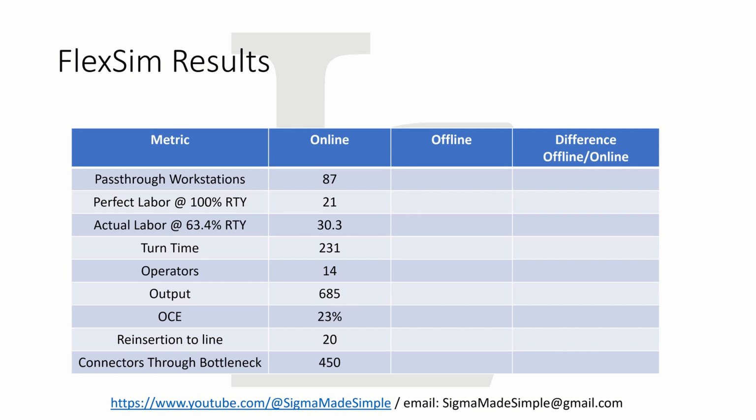and because of the way that we're dealing with our rework. The portion of lead time attributed to manufacturing is what I call turn time. Here, turn time for online rework is 231 hours. For 2 shifts, having 15 hours of working time per day, that would be 15.4 days to deliver this product. After that, you get another product off the line about every 8 hours.